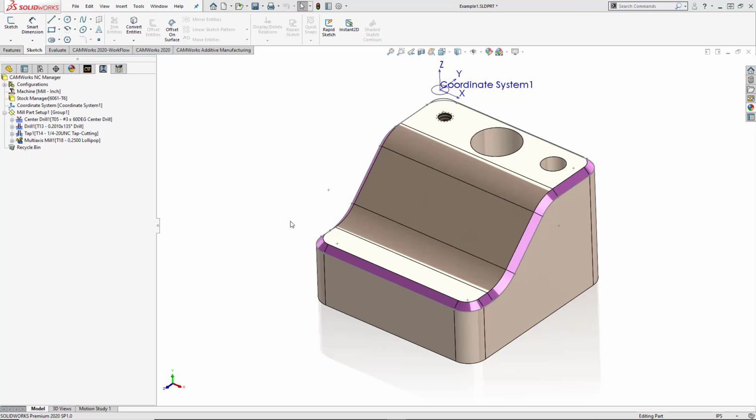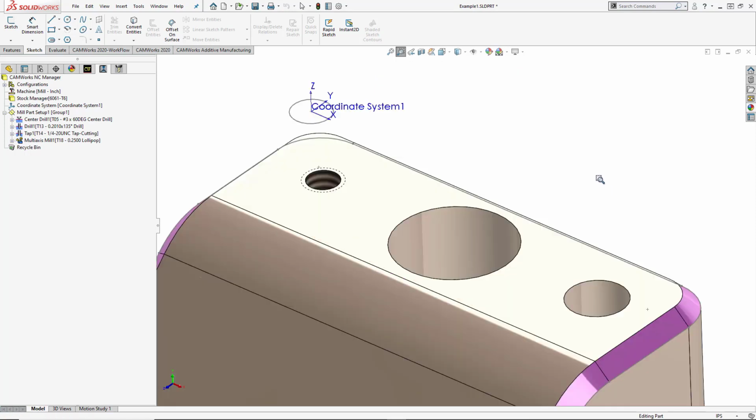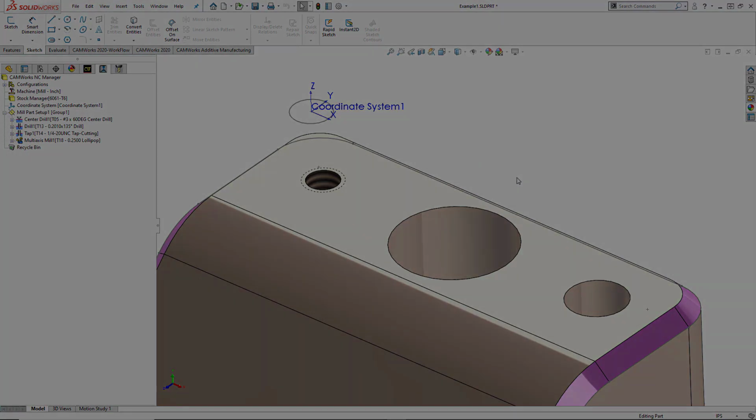Whenever faced with machining challenges, quote unquote, CNC programmers and machinists always seem to find solutions to get the job done. With that mindset, CAMWorks offers you the flexibility to easily generate helix spiral entries for circular holes and pockets to save time. By minimizing the use of multiple cutting tools, or if you have a machining center that does not have an automatic tool changer, this time savings workflow is for you.